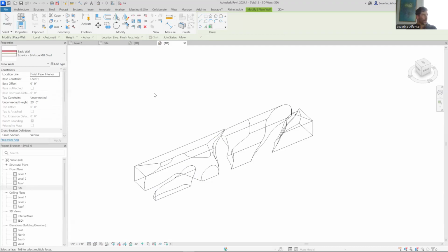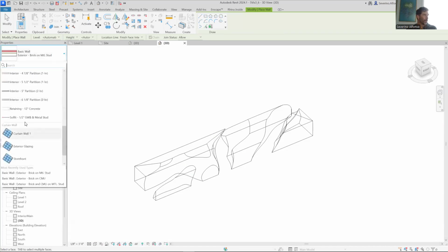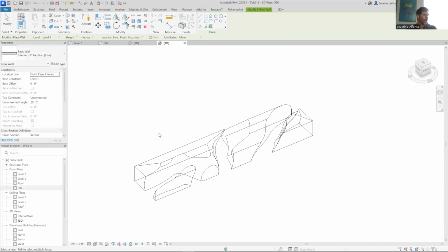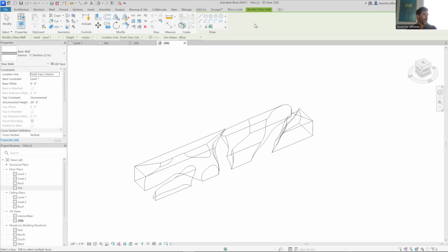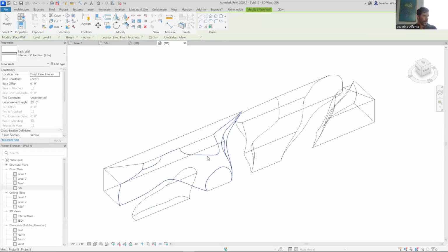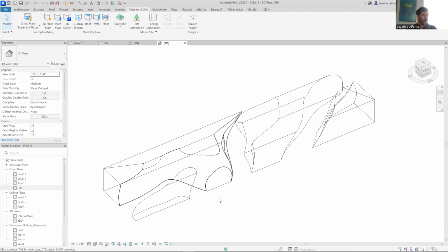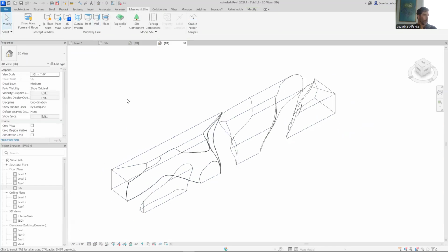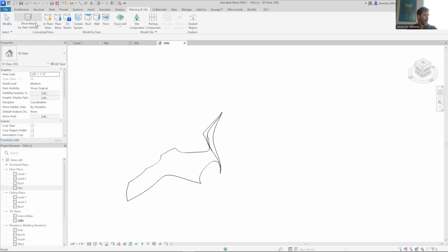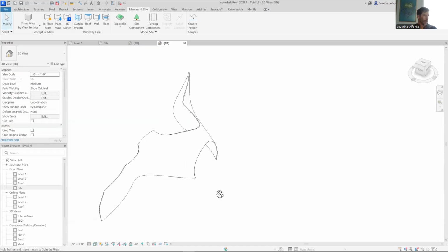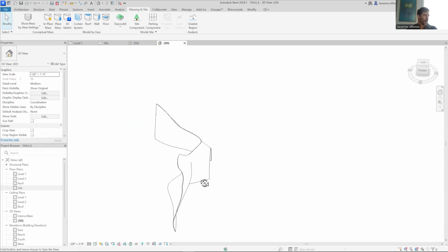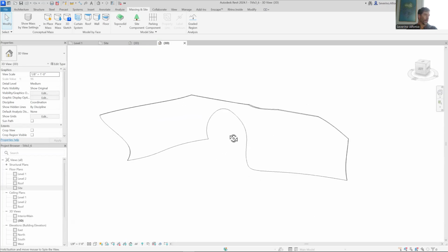So I'm going to select interior partitions, the rating. That's the type, and the option of model by phase allows you to select the phase directly. It turns blue, and then you click. I want to escape that and see what we have done. If I turn off the masses here, and go to hidden lines, it's basically a very complex surface, but it's a wall now.